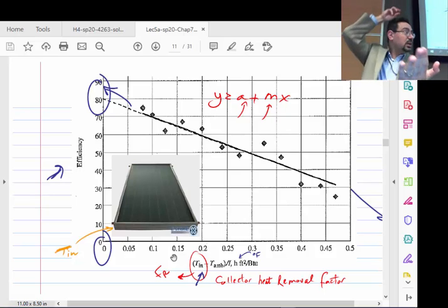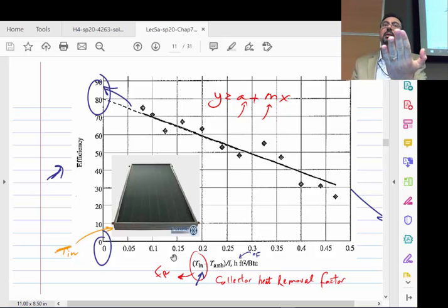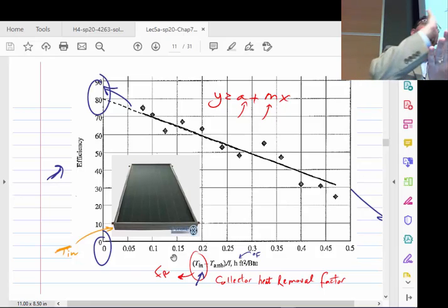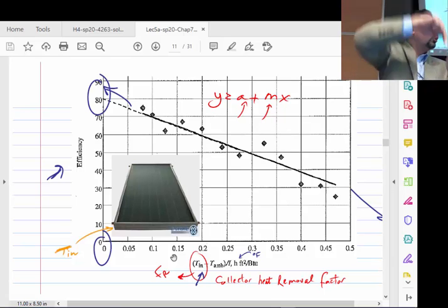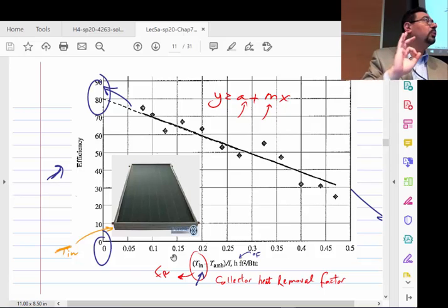So that theta I, if you did a great job in the middle of the day, should be 0, like the sun is really normal to that plate. Then the sun starts moving away, and the incident angle will increase. Worst case scenario, theta I is 90. If theta I is 90, that means the sun is parallel, not normal, to the collector, and the radiation would be 0. But even if the angle is not 90 but like 80 or 70, that's still horrible.